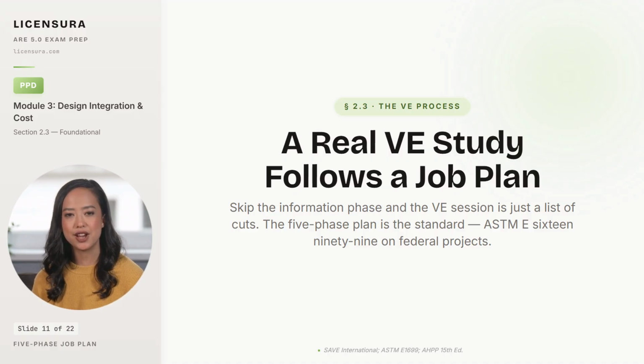the architect who recommends the wrong substitution, gets the owner sued by an end user, and personally absorbs the redesign cost. On federal and many public projects, VE studies must follow ASTM E1699, the standard practice for performing value analysis of buildings and building systems, which formalizes the same 5-phase plan. If you skip a phase, the result is not VE. It is an arbitrary scope cut wearing a VE label, and the exam will mark it wrong. Let me walk you through the 5 phases and what each one is supposed to produce.